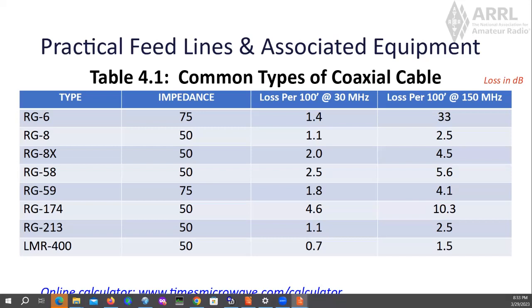But again, it is not a hard and fast number. The speed of light in a vacuum is a hard and fast number. But when that wave moves into our atmosphere, it slows down a little bit. When it goes into our copper wire, it slows down a little bit. When we use insulated house wire, it slows down a little bit. Those are all factors that you can figure in, but the better way to do it is start with the 490 number, put it up in the air, see what it does, and if it needs to be a little bit shorter, that's real easy to fix.